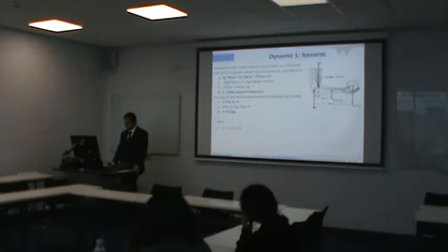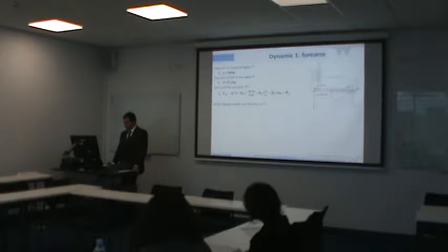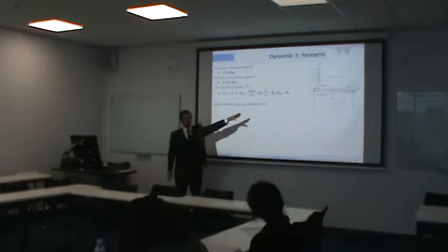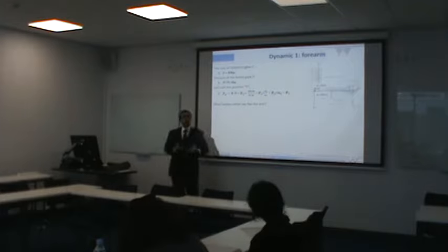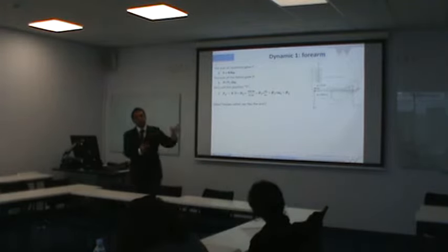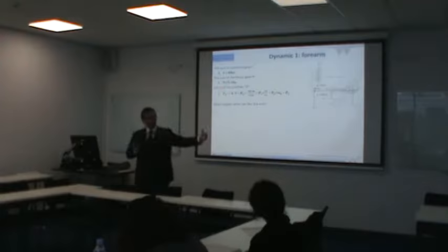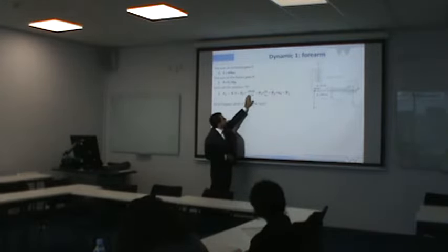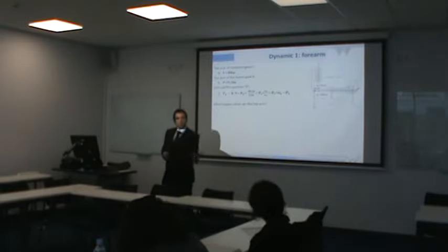Okay, here there is the mathematical solution of the problem. So if you like to try yourself, you have all the solutions. What we need at this moment is perhaps the conclusion. As you see here, the force that our biceps is opposing to the weight of the ball is about 9 times bigger, because 9 is the ratio between the 40 centimeters and the 5 centimeters, which are the distances of the forces from the joint. So there is a ratio between those two distances, which gives a factor proportional to the weight you need to lift.